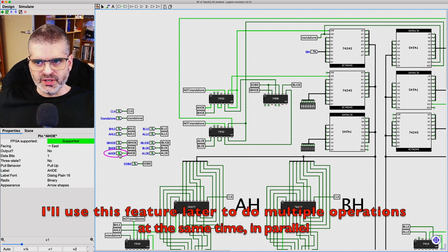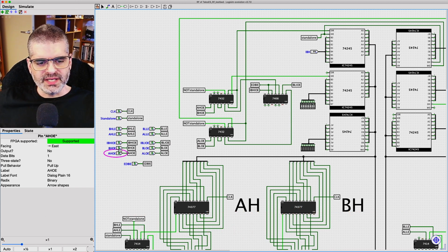Now, if I bring this back, the direction changed again, so now it's an input as opposed to an output. But if B high tries to drive the high bus, see, the direction changes again. So now the value that B high puts on the high byte of the bus will be driven out from A to B to the other cards. So the other cards know what value B high is putting on the high byte of the bus. Now, if I activate both, this is not allowed, because you cannot have 2 bus drivers, but you still have the correct direction.